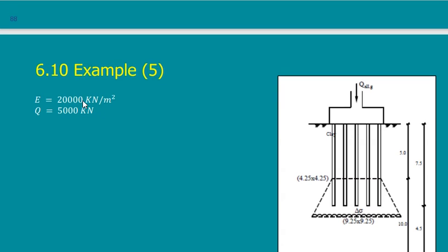This is an example. If you see this example, it's not written, but this is a friction pile. So my imaginary footing will be in the middle part, or the lower third of the pile length. This will be my imaginary footing. And this is the total from here to the bottom.